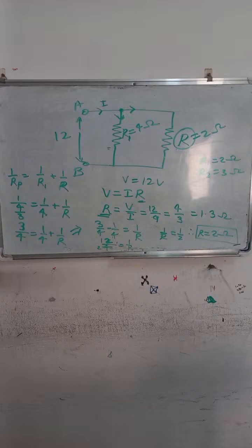Okay, here everything is given. We have to calculate the amount of heat generated. So potential difference is given 40 volt, and here charge is given 96,000 coulomb, and time is also given, that is 2 hours. So amount of heat generated is nothing but what? H is equal to V into I into T. Okay, use this formula and try to find out the answer. Okay, chalo, try this question. Charges are given.